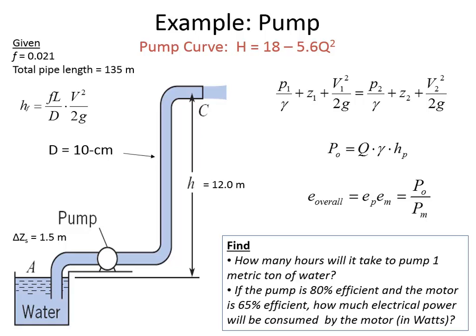This is the inlet local loss. And so the pump is going to have to apply 12 meters of head just to lift the water. And then it's going to have to add enough head for it to have velocity. And then also the local losses from the inlet. There won't be an outlet loss because the water is still moving as it comes out of that orifice.